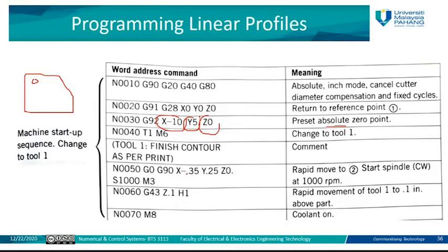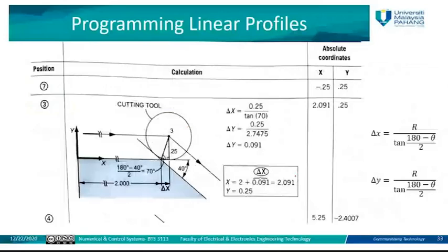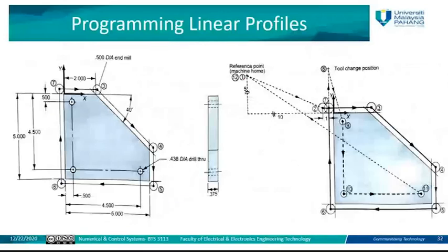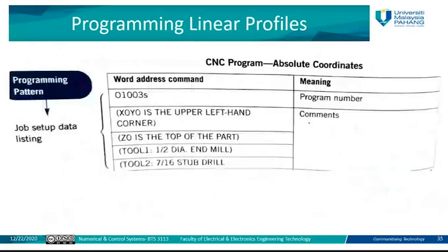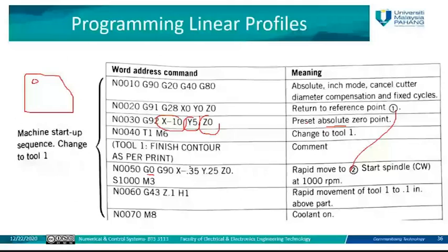Then you go rapid movement. We said G0 here will move the spindle to the specific point to start to move. So here the spindle will move from point number 1 to point number 2, as we already mentioned before, this is the reference point. Now it will move without any operation in between 1 and 2, because the part is still there. When the spindle moves from point 1 to point 2, it is just a fast move. Until now, we didn't start our milling process. For that, we do not have G1 here, only G0.